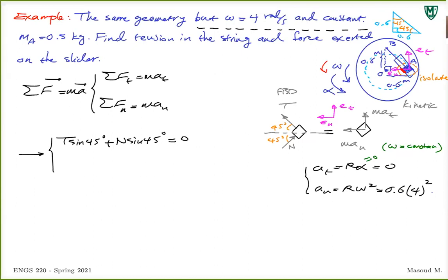What does this tell me? Interesting. So I concluded that the normal force should be in this direction, the direction I put on this free body diagram. I said it should be in this direction based on the direction of omega. Alpha is not given, so I just made that assumption, because I don't know if it's accelerating or decelerating, or how that affects the normal force.